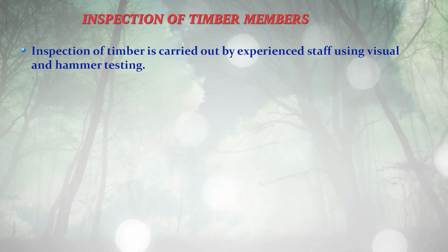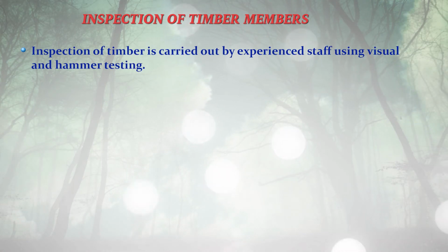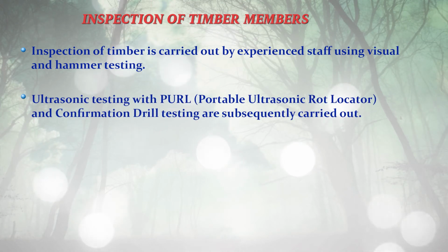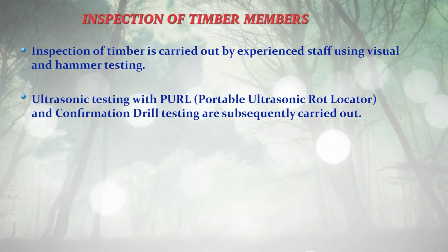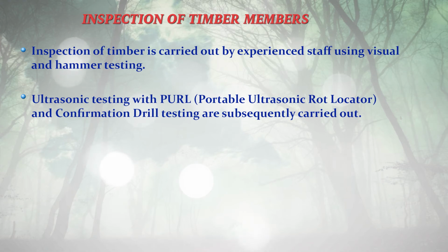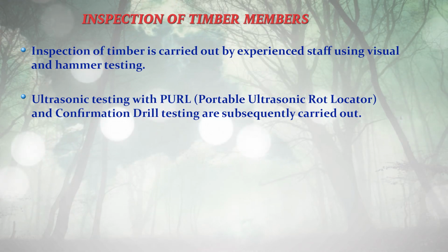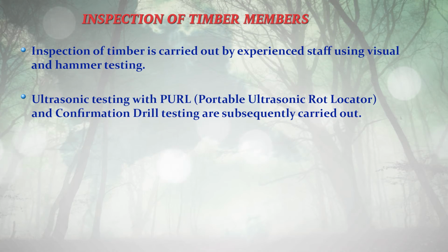Now we move to the inspection of timber members. Inspection of timber is carried out by experienced staff using visual and hammer testing. Ultrasonic testing with PURL, which means portable ultrasonic rot locator, and confirmation drill testing are subsequently carried out.